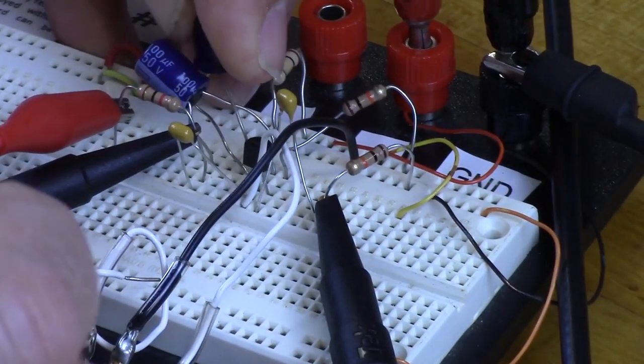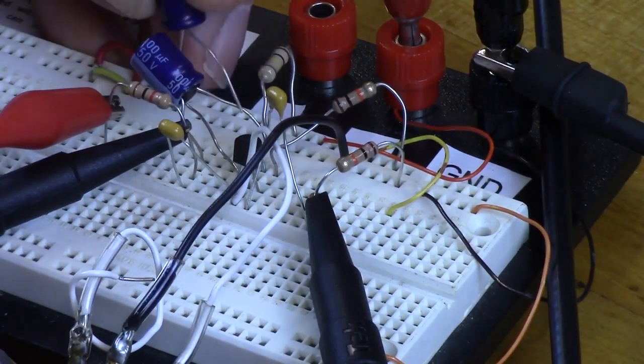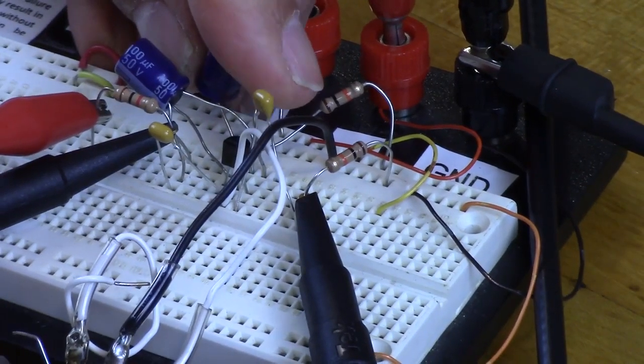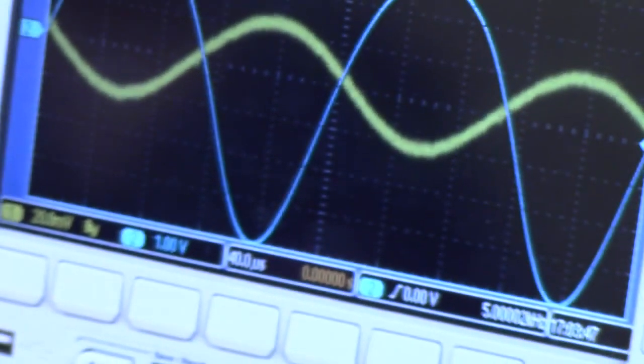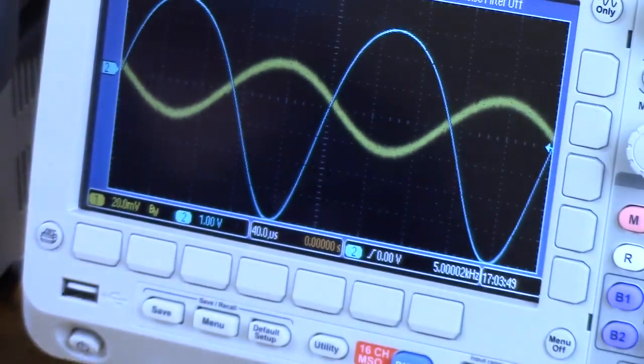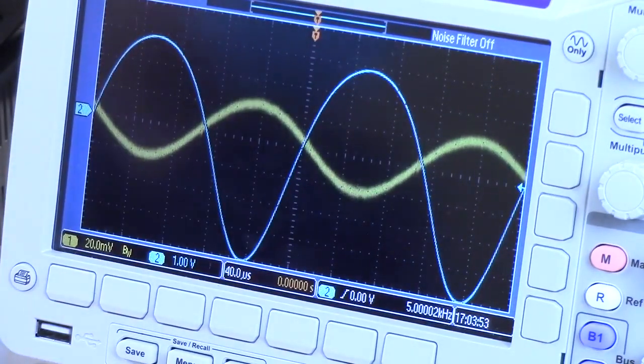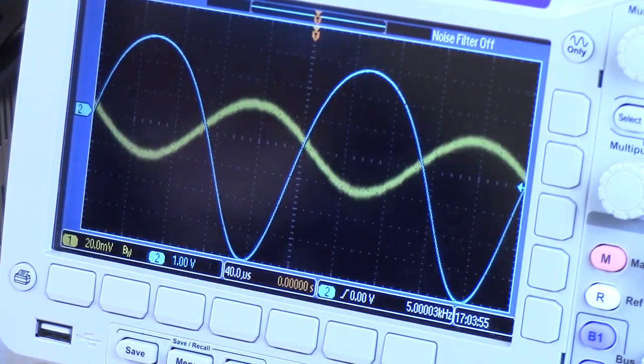CE to there. Like that. So now we can be sure that the emitter is completely bypassed, and the only pole we're going to see now is due to C2. C1 and CE poles have shifted all the way to the left, and we're looking at C2 by itself.